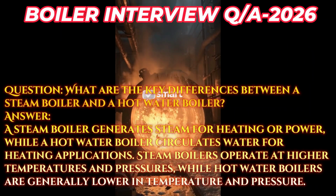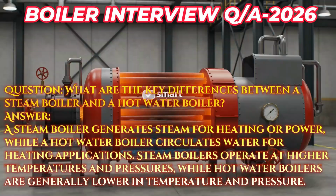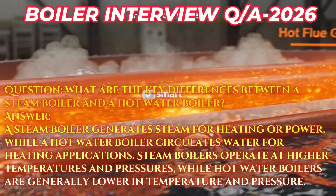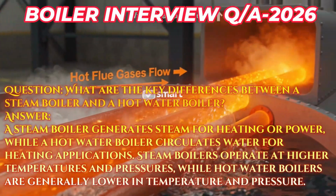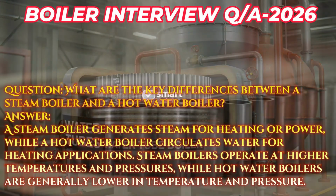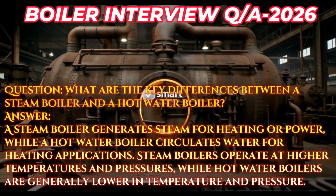Question. What are the key differences between a steam boiler and a hot water boiler? Answer. A steam boiler generates steam for heating or power, while a hot water boiler circulates water for heating applications. Steam boilers operate at higher temperatures and pressures, while hot water boilers are generally lower in temperature and pressure.